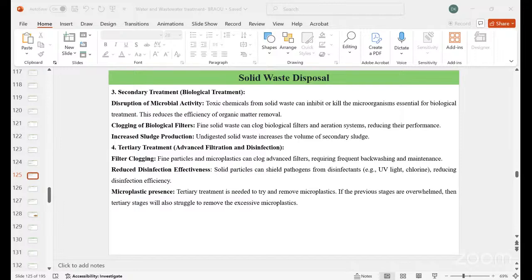So coming to the electric arc plasma incineration process, which uses a plasma torch to generate extremely high temperatures, up to 5000 degrees centigrade, or even more, up to around 14,000 degrees centigrade. It will go up based on the usage of the product. At this high temperature, it mainly breaks down the waste into basic molecular components.